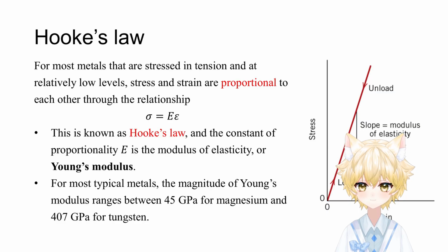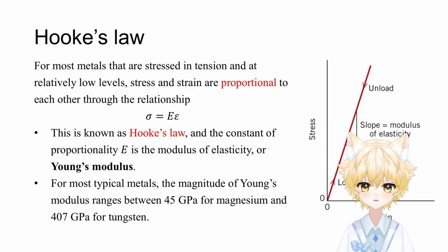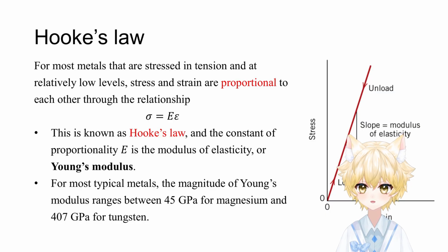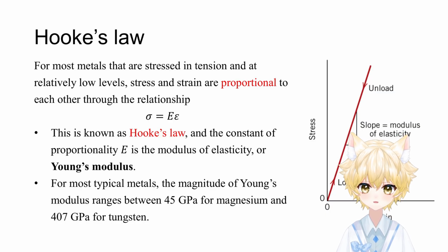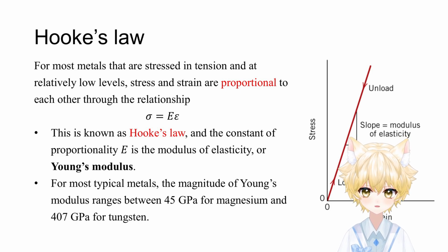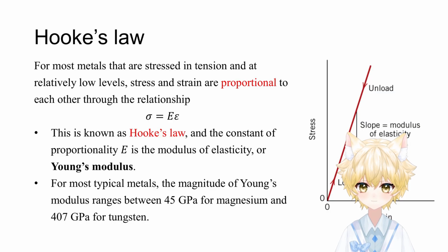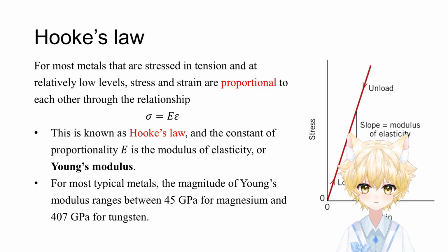This modulus may be thought of as stiffness, or a material's resistance to elastic deformation. The greater the modulus, the stiffer the material, or the smaller the elastic strain that results from the application of a given stress. The modulus is an important design parameter for computing elastic deflections.